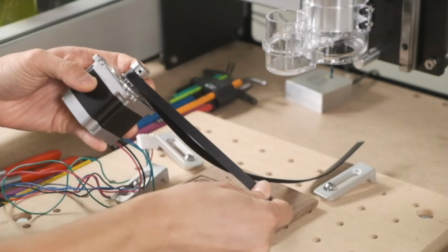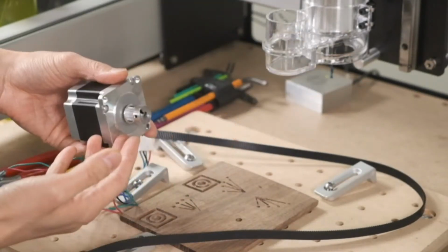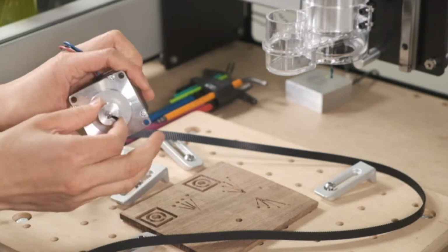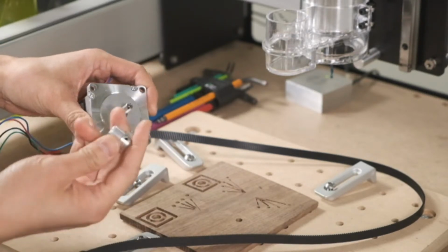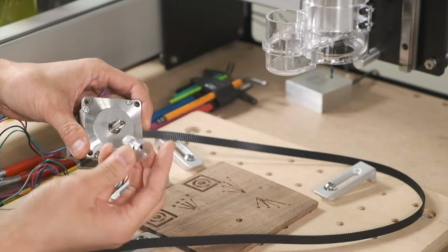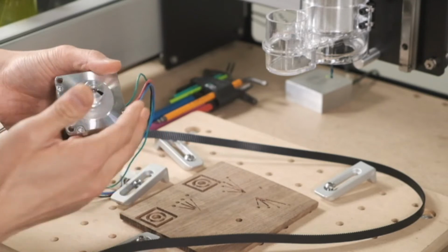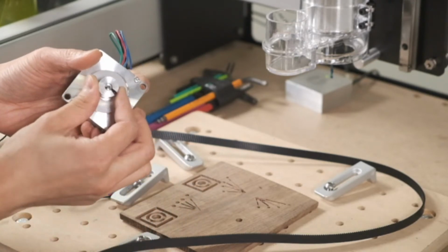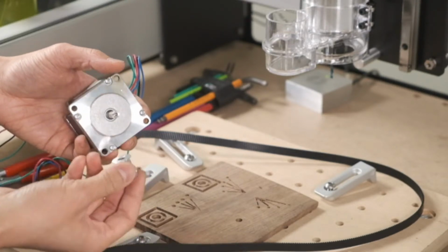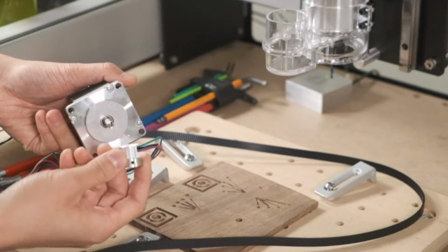As the pulley rotates, it moves the belt. The first part of this drive chain that can potentially be at error is the whole pulley to stepper motor interface. There are two set screws on this pulley, and if these are not tight, your pulley can slip on the stepper motor shaft. So the first place to look if your machine just isn't moving, even though you might hear the stepper motors clicking, is to make sure this isn't slipping. Sometimes these get loose, sometimes these need a drop of thread locker to keep them from backing out. If you've been using the machine for a while and all of a sudden it stops moving, check your pulleys.